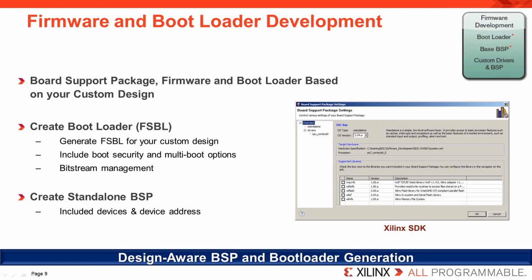Within any system that utilizes a processor, firmware plays a crucial role. As we described a couple of minutes ago, Xilinx SDK already includes a full C and C++ development environment for application and library development. To address firmware development, SDK uses this same environment along with its ability to understand a XPS-defined custom design. When these functional SDK capabilities are combined with Xilinx-provided source code, reference designs, and technical documentation, developers have everything needed to create a custom first-stage bootloader, including secure boot and multi-boot options, or a standalone board support package.